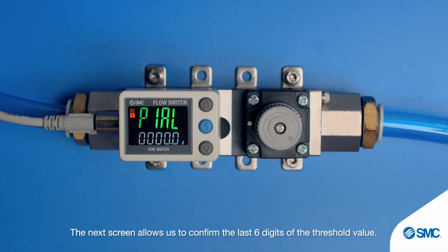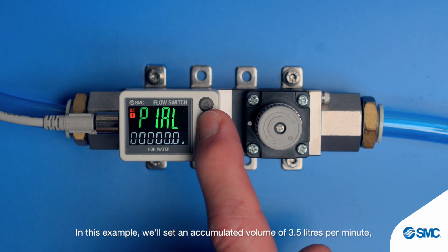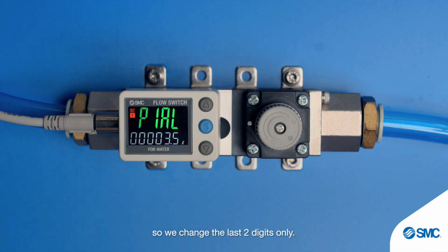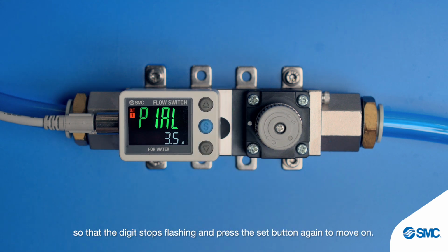The next screen allows us to confirm the last 6 digits of the threshold value. We can modify each digit using the same method. In this example, we'll set an accumulated volume of 3.5 liters, so we change the last 2 digits only. Again, to accept the entry, hold the set button for more than 1 second so that the digit stops flashing and press the set button again to move on.